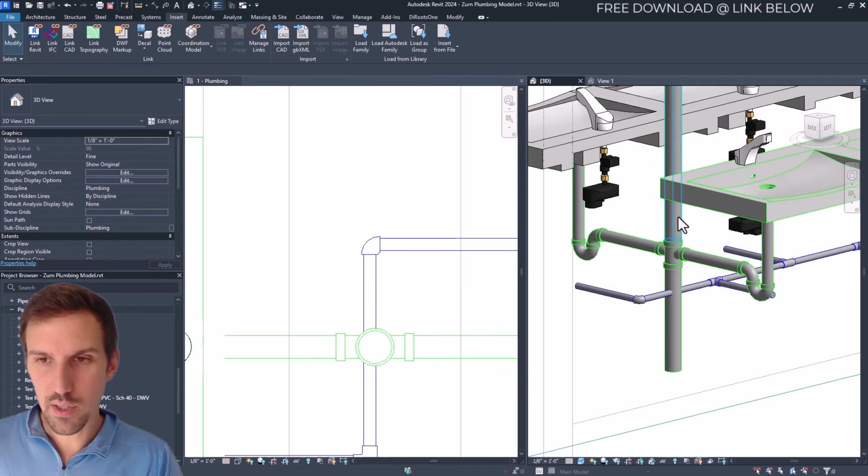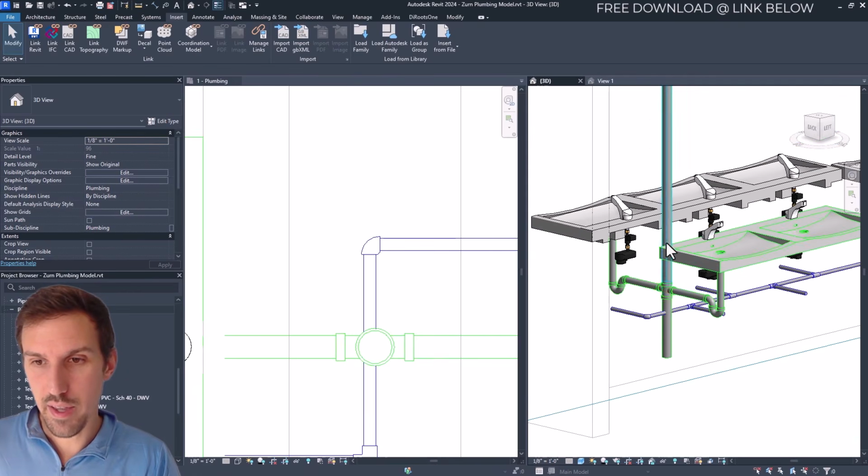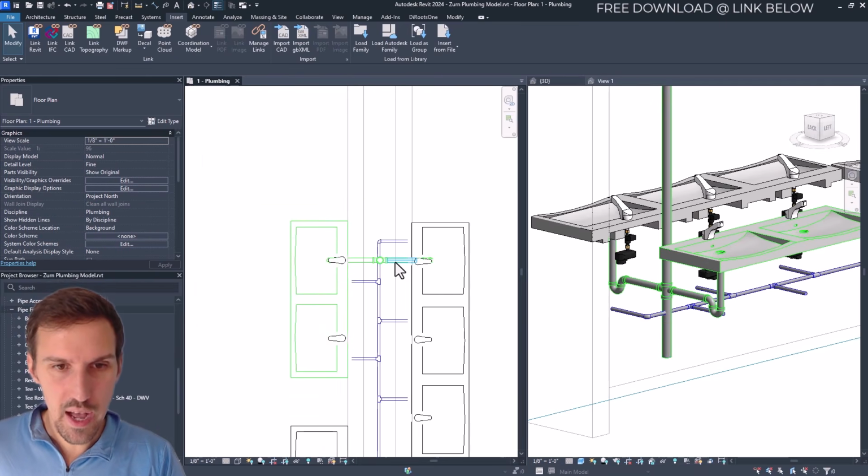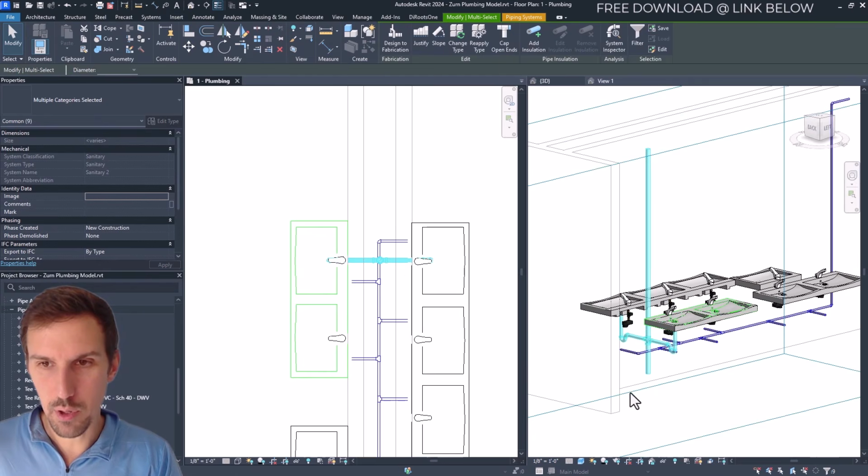Now this is what's called a common vent. And the reason we call it that is because this pipe right here is venting both of these fixtures. Okay, so it's a common vent. All right, so let's essentially just copy our common vents each time we have these lavatories back to back like this. So I'm going to tab into all of my pipe here by clicking tab on the pipe multiple times.